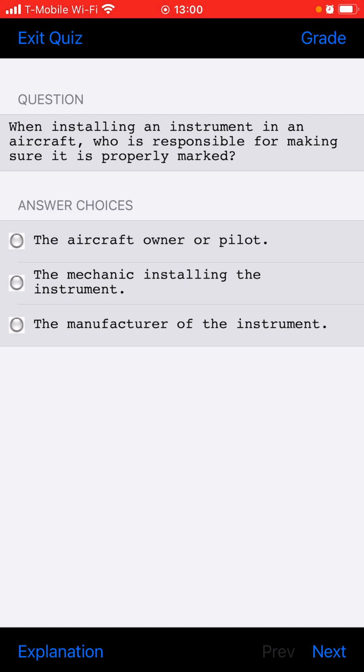What mechanism ensures that the nose wheel is not turned as it retracts into the wheel well? The internal centering cam in the strut or external track.